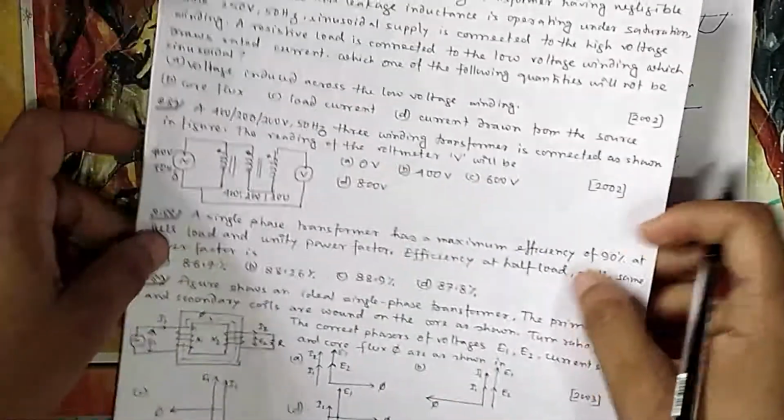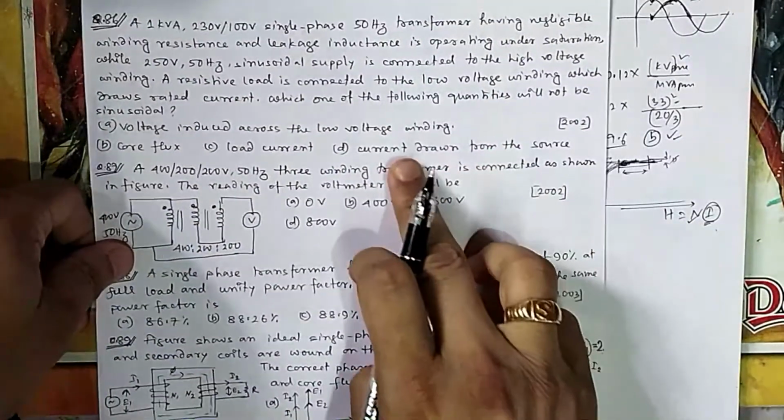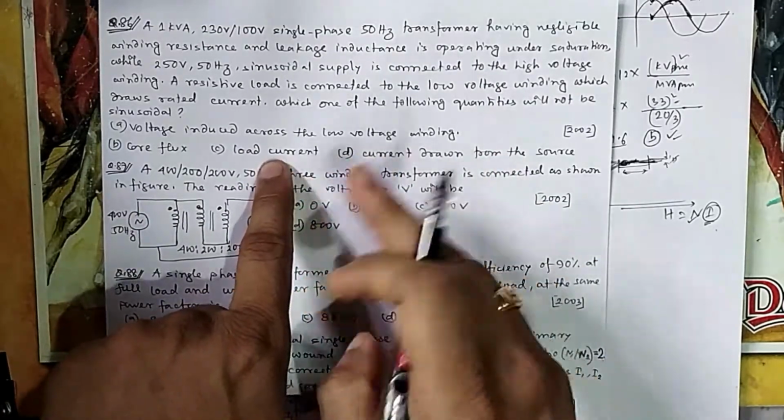So current drawn will be more peaky in nature. So that is the current drawn. LEDs will be always same as sinusoidal. So current drawn from the source will be more and more peaky. It is not load current. Load current will be again sinusoidal.